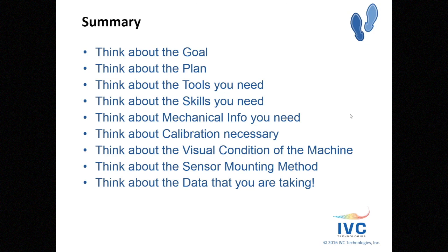Will you need calibrations for the test that you're conducting? You may have to send out all of your equipment for calibration to have fresh cal sheets before I get to the site to conduct the test, because I'm going to have to provide them on the back end. Think about the visual condition of the machine. Don't blindly follow routes or just take data. Pay attention. Look at the thing while it's running. It's going to help fill in a lot of the blanks. Also, think about the sensor mounting method. Make sure that you're using the appropriate method for the test that you're conducting.